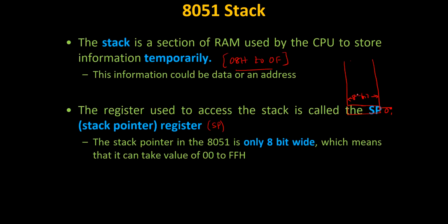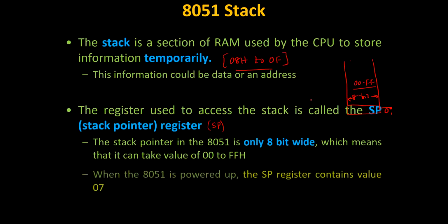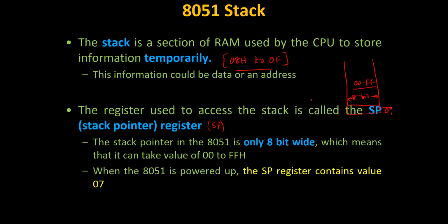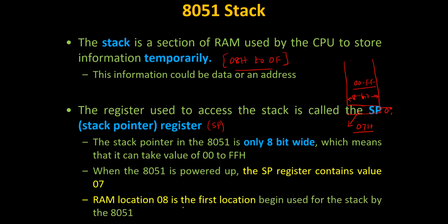When the 8051 is powered up, the stack pointer points to the top of the stack, that is 07H. RAM location 08 is the first location used for the stack by the 8051. After 07, the next location is 08. So this is the beginning of your RAM.